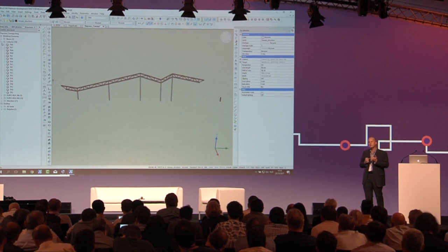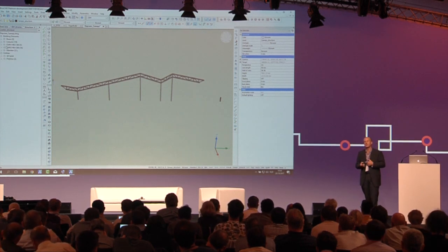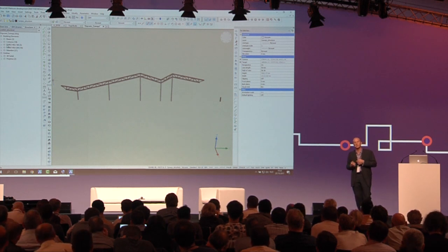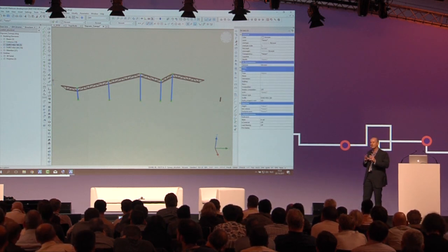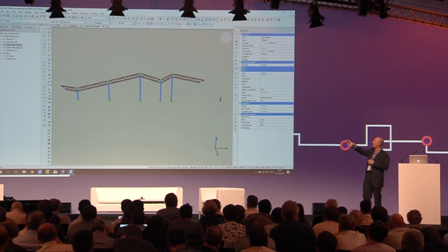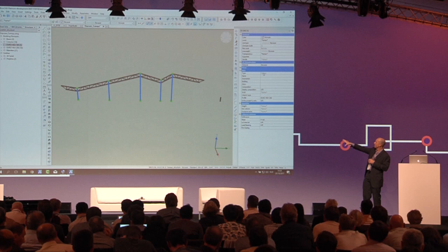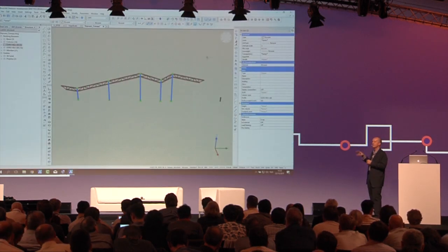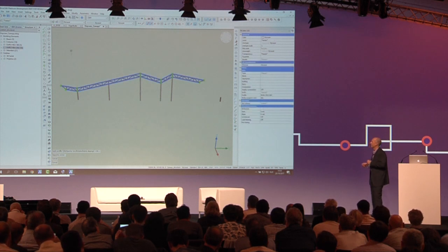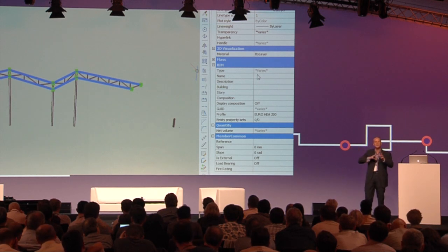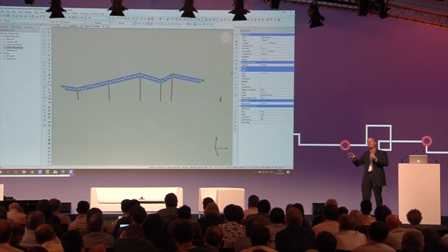And one of the things that Bricsys BIM is doing also behind the scenes is that it's auto-classifying the elements, the structural elements that we create. And we can check if things are looking the way we want them to. So by selecting the profile, we see that all of those 5 columns are identified as columns. If we select the next profile, which is a combination of elements at different slopes, chords at different slopes, it's showing varies, which means it's interpreting it as both columns and beams.